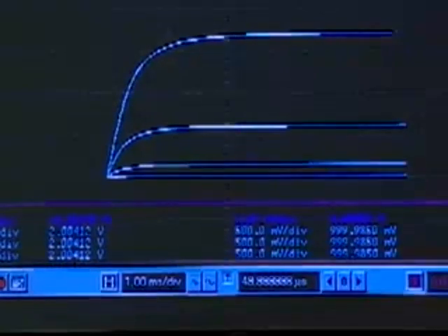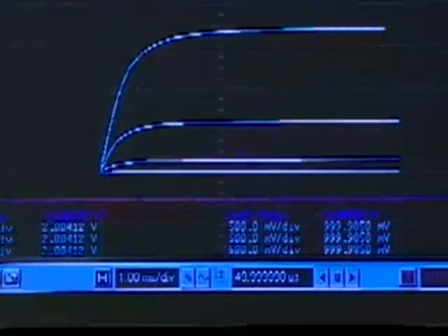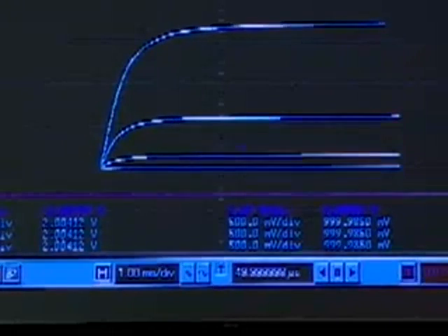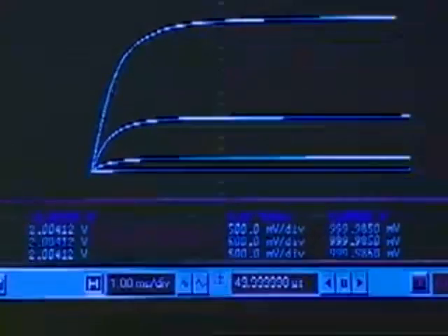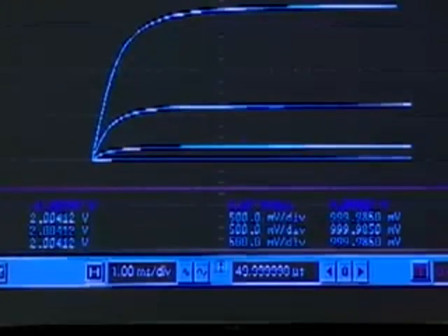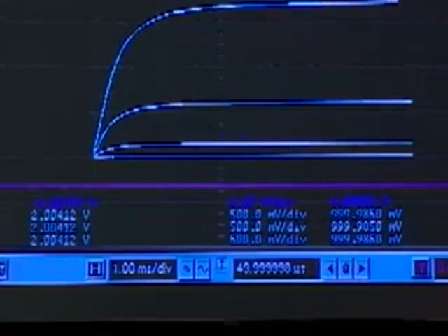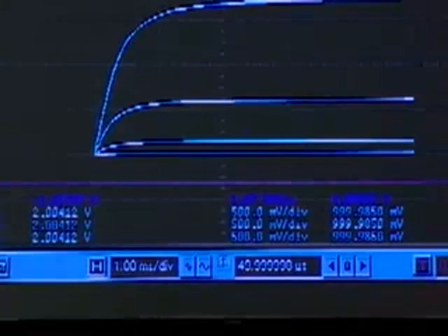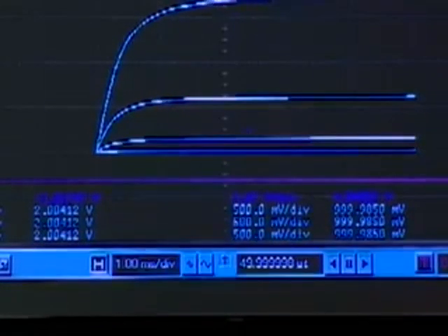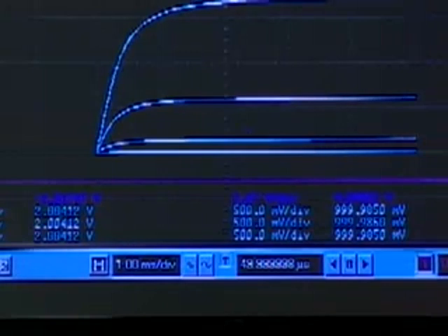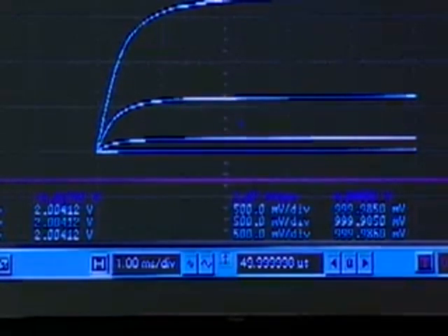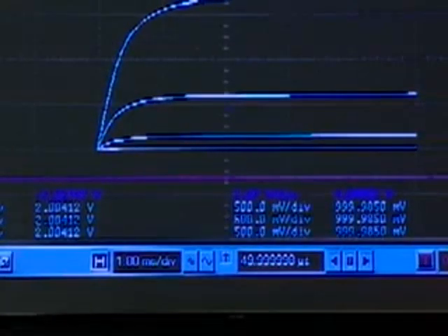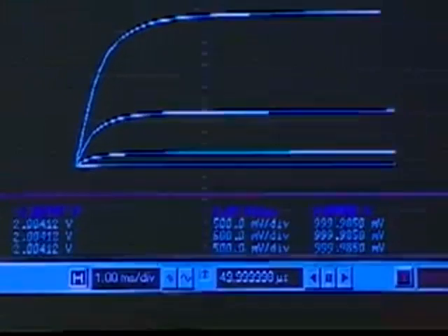This line up here corresponds to the output voltage, VO. What I'm going to do now, through some careful circuit hacking, is show you a load line and the bias point, and show you how the bias point can be moved up and down by changing the input voltage, which changes the corresponding output voltage. It's hardly visible out there.